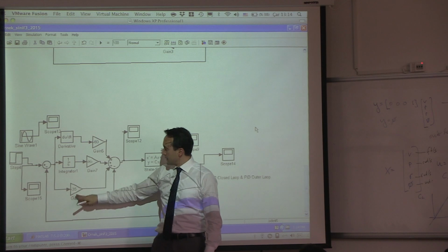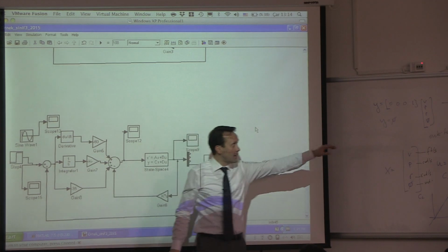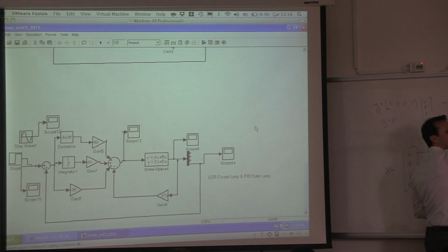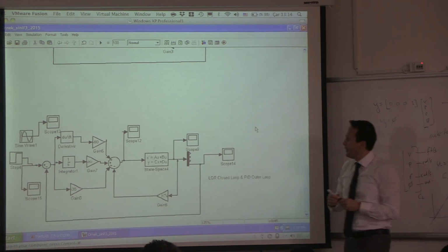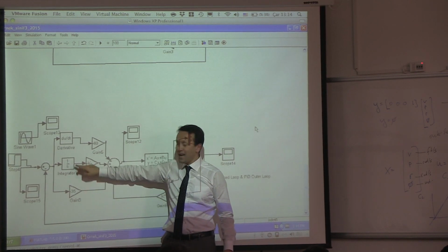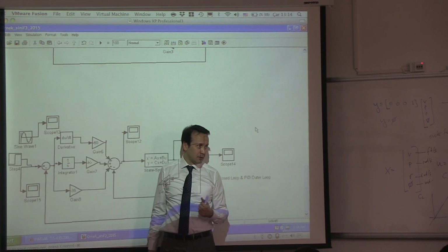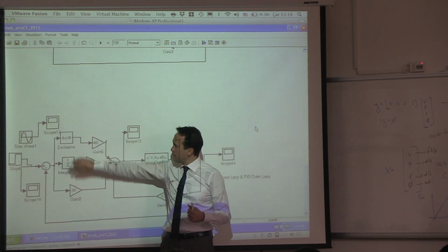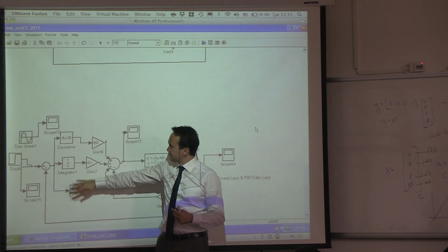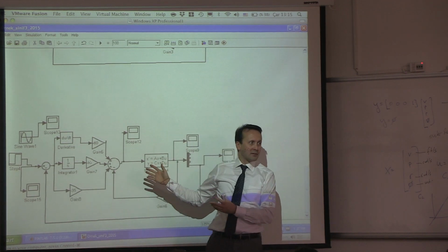So it will be like, see, if you don't have the integral and the derivative, you just have the gain. It is a tracking controller I designed over here. This would be a P controller because you just have a proportional control. Okay? If you have the integral here, this would be an integral controller. If you have integral and proportional, you have a PI controller. If you had a derivative on top, you would have a PID controller. Okay? Now, I didn't do that too much. You can, of course, do these things. But at the end, the architecture for a PID controller is, again, the same thing.